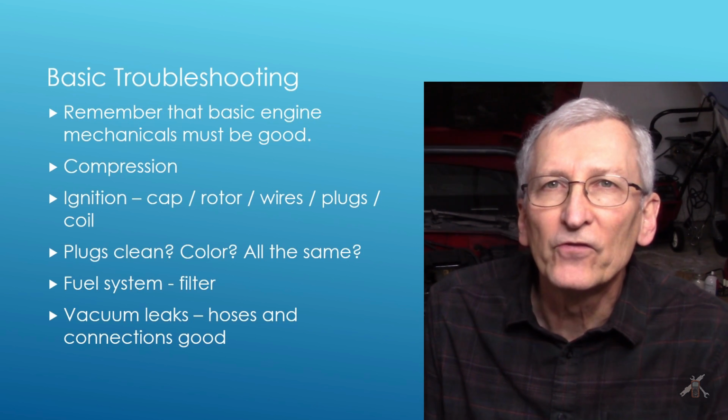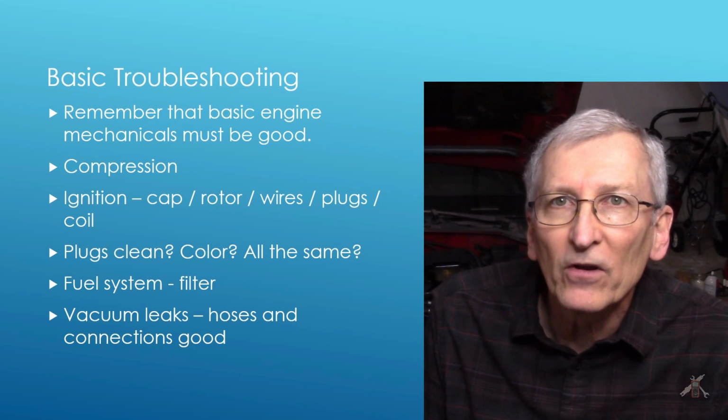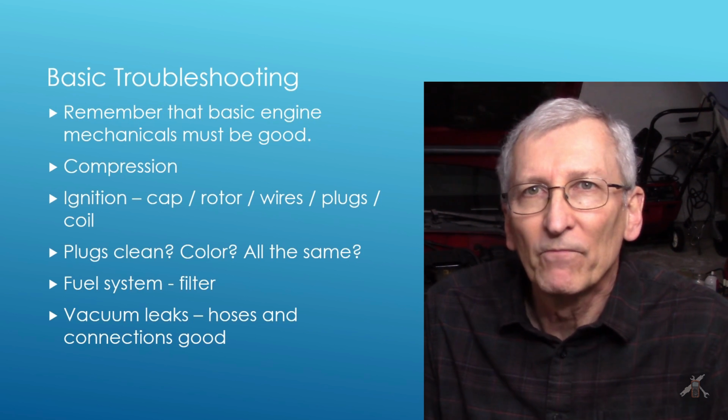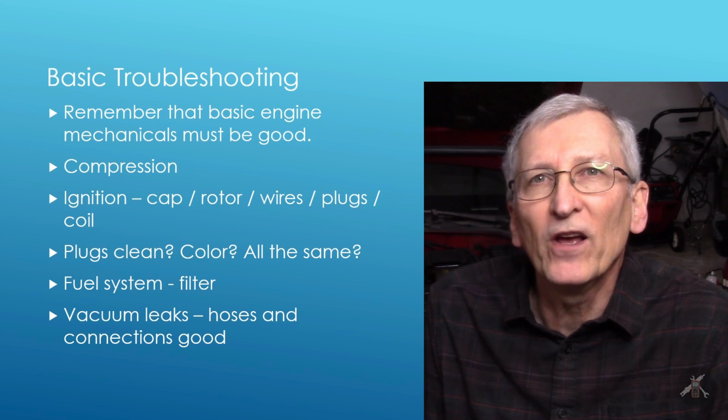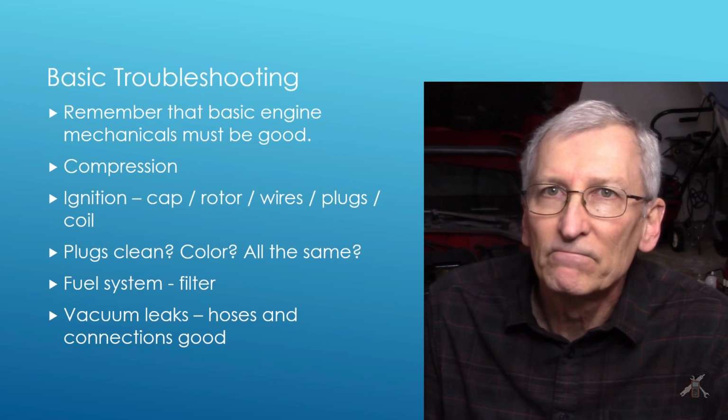If you've got these older engines, most of them have PCV valves on them. Does your PCV valve work? Does it rattle? Is it clean? Any of those things will upset your computer and cause it to not be right.